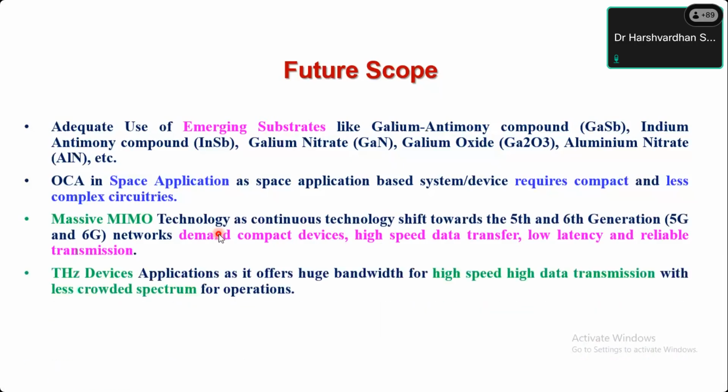Moreover, terahertz devices, because at terahertz frequency the wavelength is very small. So even if you are designing a lambda by 2 antenna, it will fit perfectly inside the chip. So in terahertz applications, why are we not using it in India? Some issue is there with the facilities, like measurement facility restrictions. The components that normal institutes generally have are not suitable for the measurement and characterization of terahertz devices. So we are limiting ourselves to microwave and some mm waves.